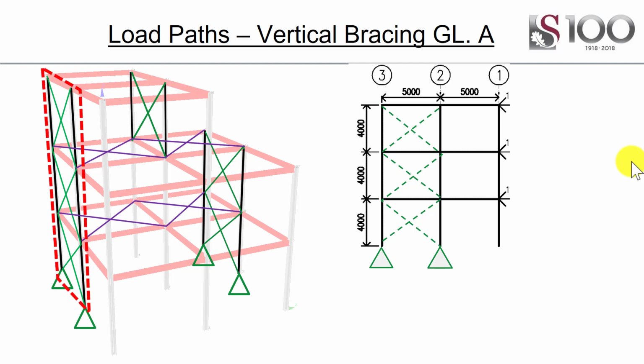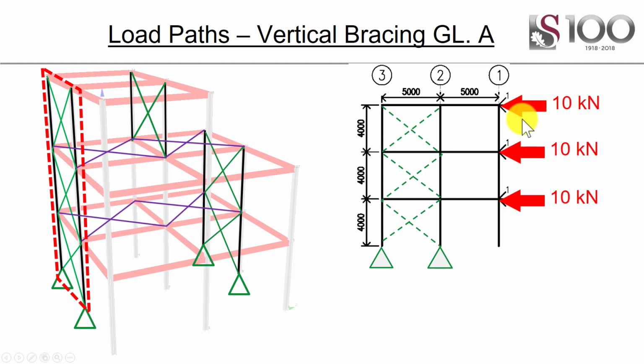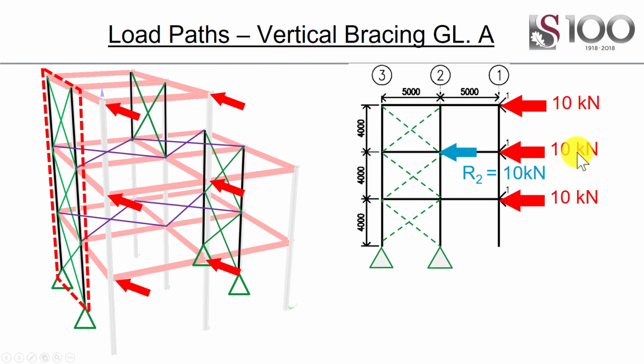So I'm going to start then with the left-hand side, and just remember I've got loads from 2 sets of floor bracing and then the lateral loads applied. So once again, there's my lateral loads. I've added on now the next 3, so now I've got 6 loads I have accounted for, and then I've got my second floor bracing, my first floor bracing, and then if I go through that, that will be where I've got compression, and then tension in all those diagonals, compression through the floor members, so those floor beams would also have to be designed for compression.